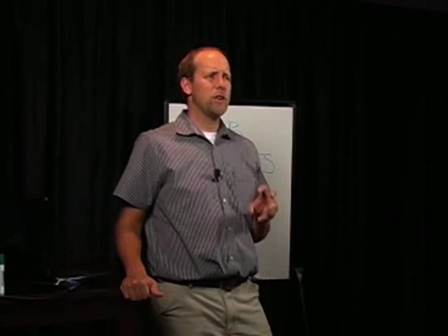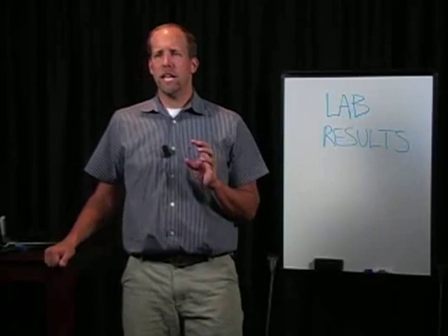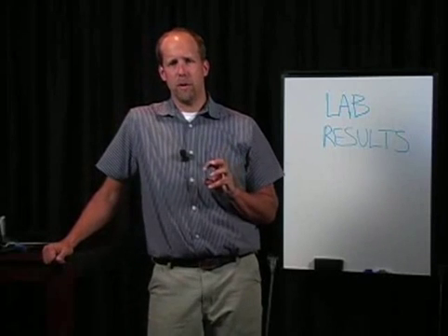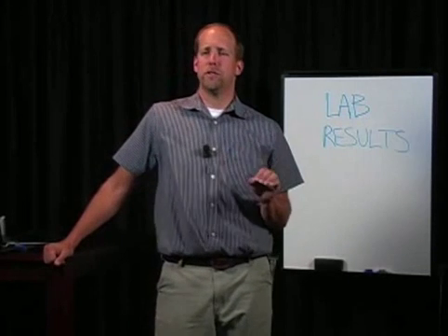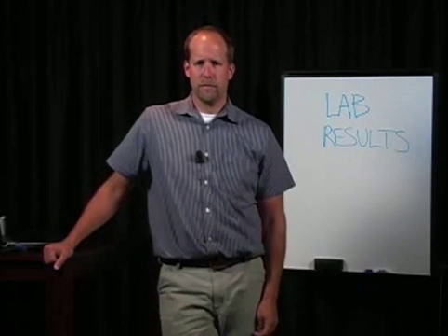Water should be removed from upholstered furniture with a water extraction vacuum, a really powerful wet vac. Completely drying upholstered furniture within 48 hours may be difficult. So if the piece is valuable, you may consider consulting a restoration or water damage professional who specializes in furniture.